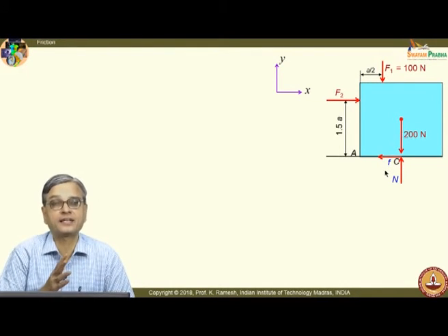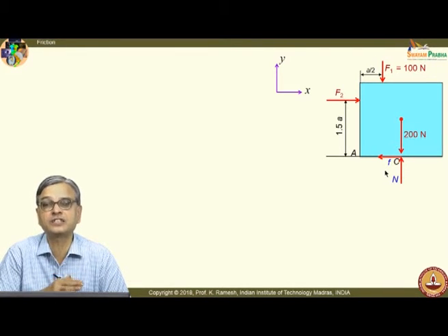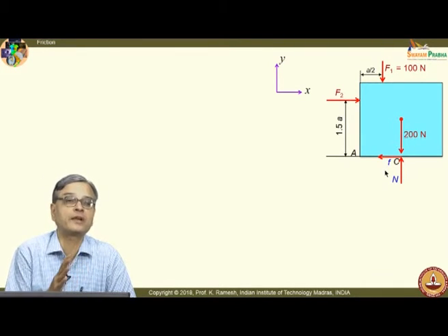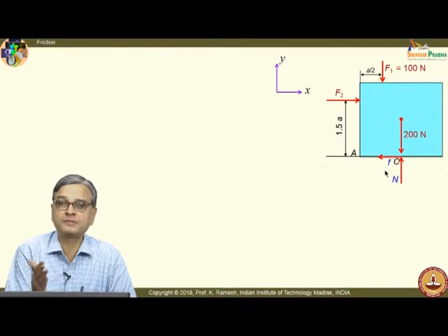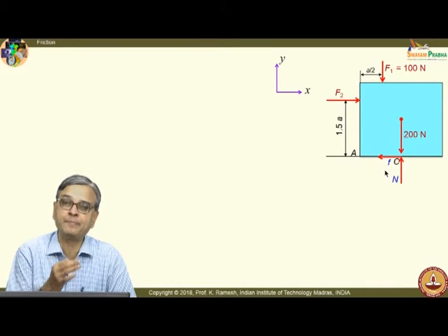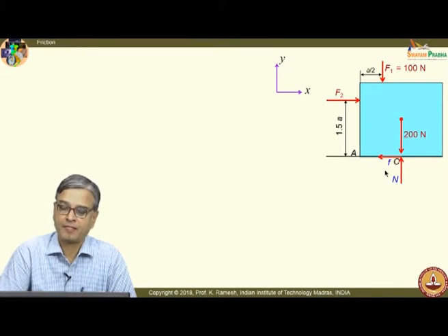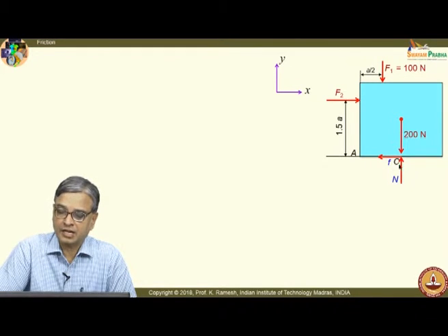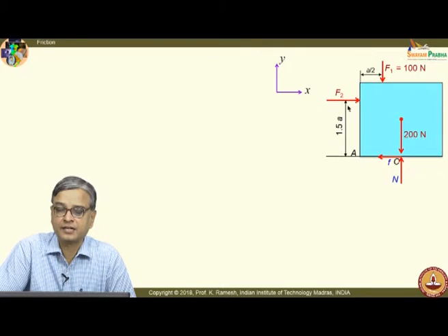You know, this is a good practice. Do not replace the frictional force as mu times the normal reaction. Never do that. Although in very important problems this might be true, in general one can coin a problem where this has not reached the maximum frictional force. Only when the motion is impending, you are allowed to write that. So, there is always a good practice to write this as f, and the frictional force direction is quite alright. I have this opposing the force that is applied. So, this direction is alright.